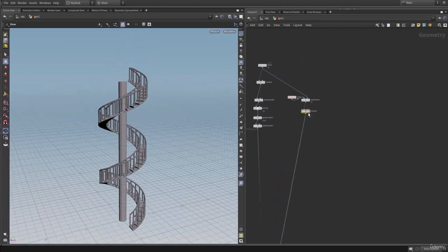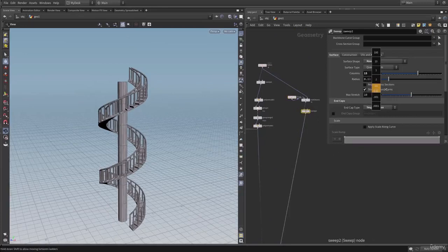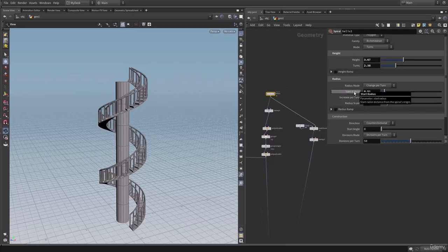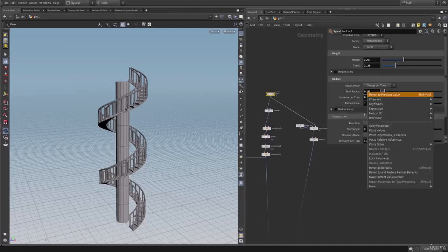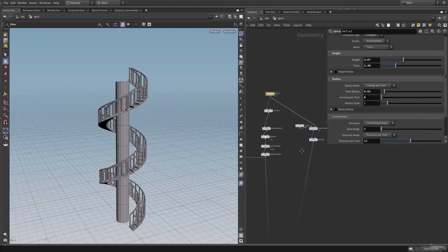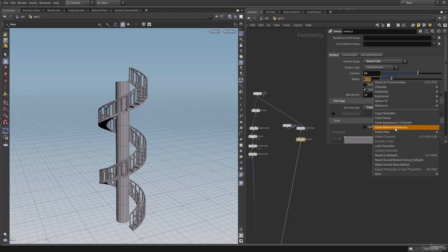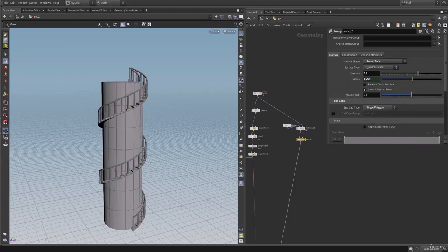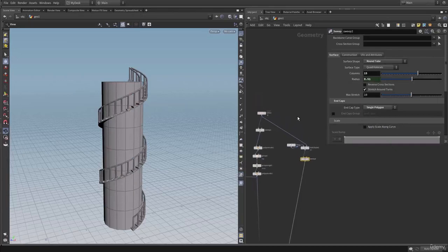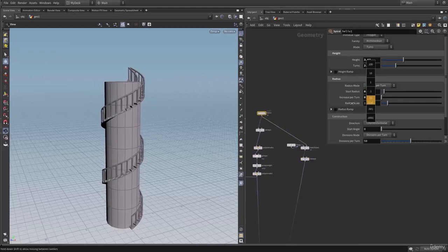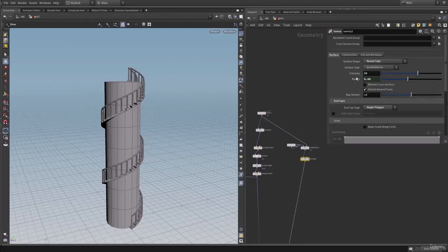And here onto its radius, let's link this radius with the helix radius. Where it says start radius, let's copy this parameter. We can say copy parameter, and onto the sweep, onto the radius, select the paste relative reference. So now we are basically referencing our scale. Whatever scale we define here, this parameter will control this parameter.